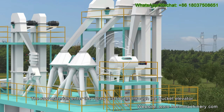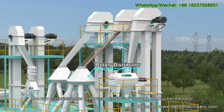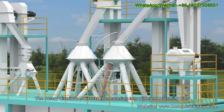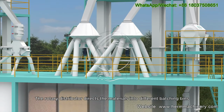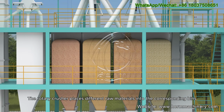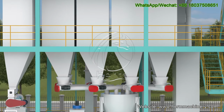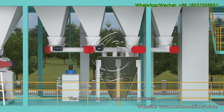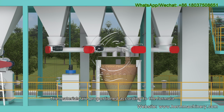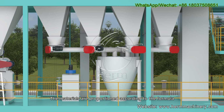The raw materials enter the rotary distributor through the bucket elevator. The rotary distributor directs the materials into different batching bins. The rotary distributor places different raw materials into the corresponding bins. The PLC computer controls the process. It directs different raw materials into the batching scale. The materials are proportioned according to the formula.